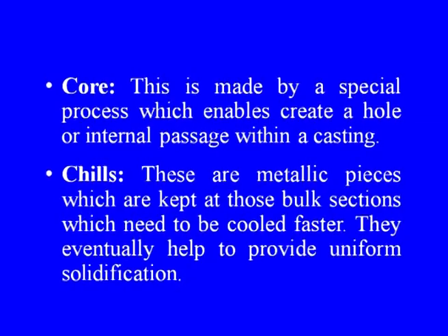Let us see a few basic terminologies associated with casting technology. This will be useful throughout this module, because we will be dealing with most of the casting techniques at various points of time. Some of these are illustrated through sketches in figures 2 and 3 later on. One very important terminology associated with casting is core. This is made by a special process which enables us to create a hole or internal passage within a casting, which is very important as far as casting technology is concerned.